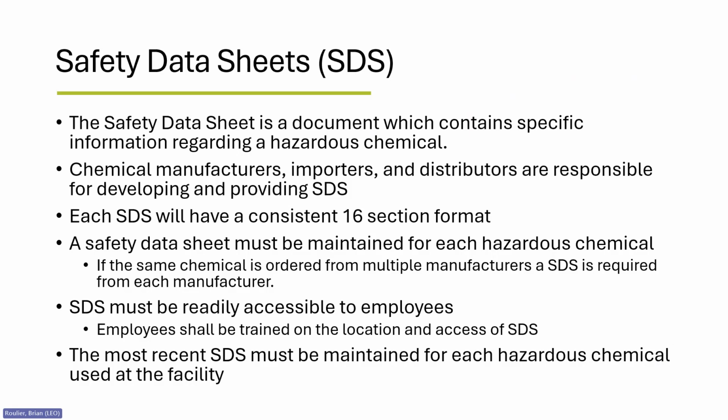Safety data sheets must be maintained for each hazardous chemical at the facility, except for those exempted in the scope which we discussed earlier. An important note is that if a chemical is purchased from multiple manufacturers, such as bleach or mineral spirits, an SDS from each manufacturer must be kept. Each manufacturer may formulate their products slightly differently, with differing compositions or hazards.